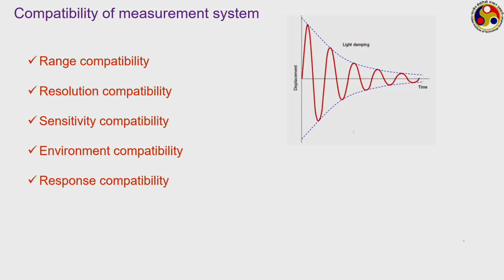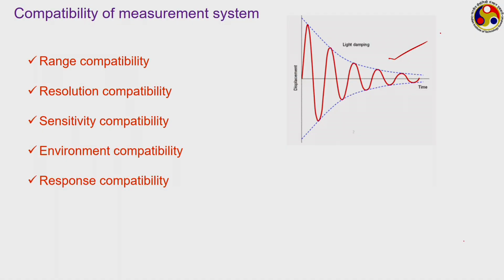The displacement of a pendulum, the signal that we got in the previous slide, is like a perfect sinusoidal wave, when it is not facing any kind of hindrance from the surrounding air. But if the surrounding air puts a significant amount of resistance on the motion of the pendulum, that will act as damping, resulting in this kind of signal, where the displacement will gradually come down. Unless we supply some additional energy, the displacement will keep becoming smaller, and after a significant duration of time it can come back to a complete standstill position.